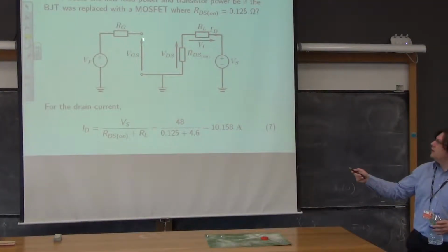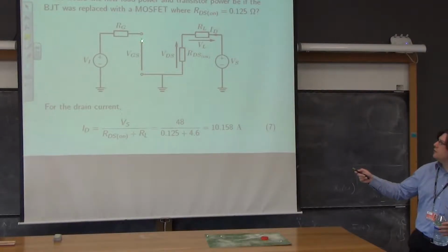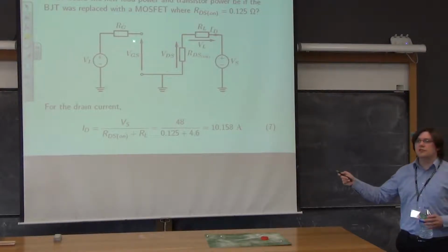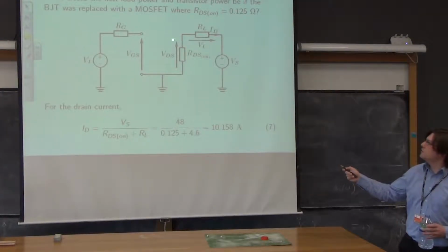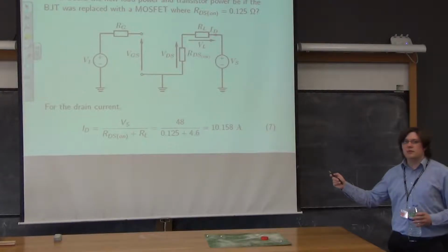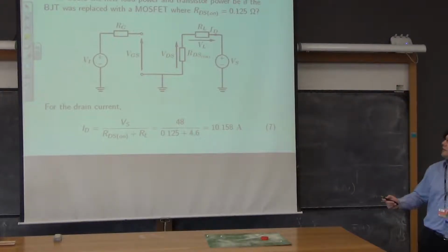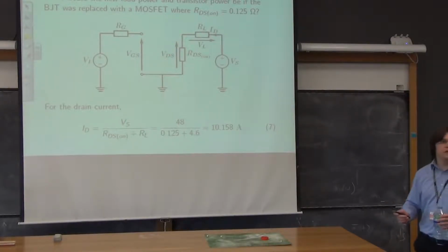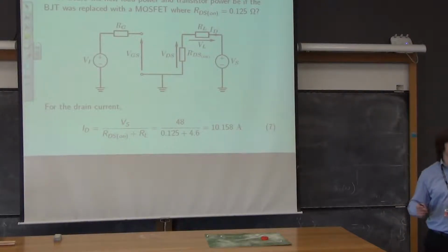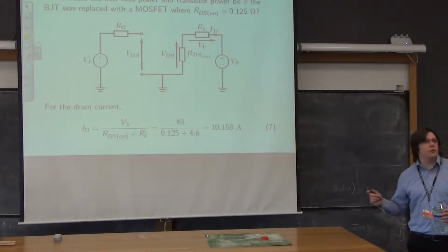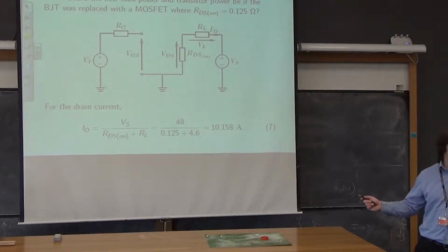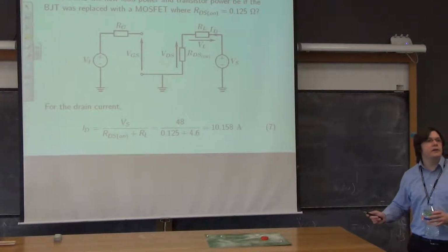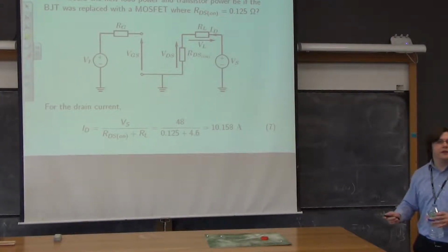So we have a new large signal model for our MOS transistor, and the difference now is that we have no saturation voltage between the gate and the source, and no saturation voltage between the drain and the source. Instead, we've got a resistance RDS on, which you can pull off the data sheet. But as we said a couple of lectures ago, RDS on actually varies quite a lot with ID, but from the point of view of what we're about to do now, we will say there is one value of RDS on, and that is as far as we will take it.